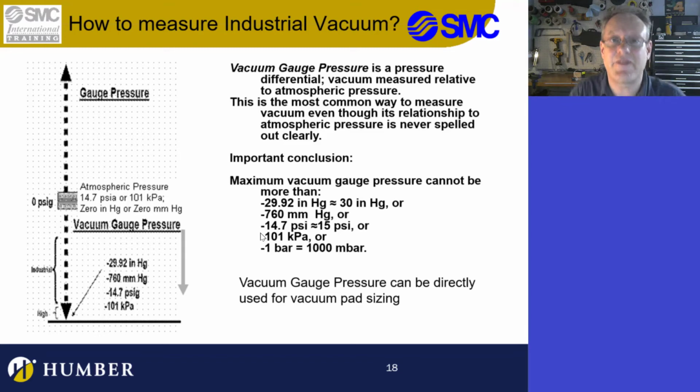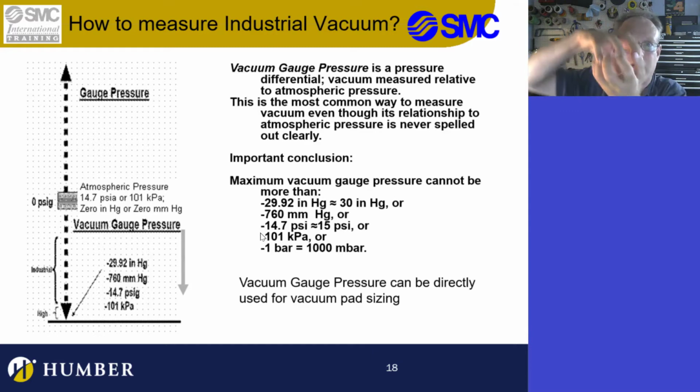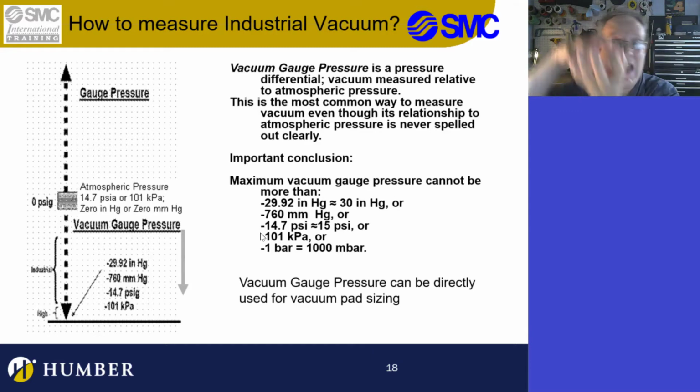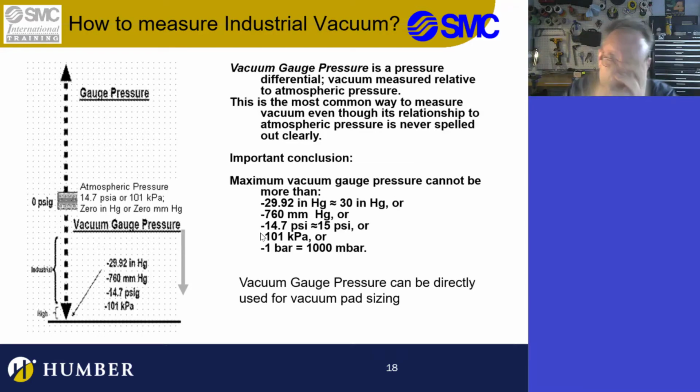Okay, so the difference, if I created a space, if I put, like, I don't know, here I have a vessel, pretend vessel. There's a vessel, and there's 2 psi in there. There's a lot less air pressure than there is out here. So the difference between the two is 12.7 psi. Okay, so there's actually 12.7 psi of pressure creating force to push that thing together. So we've got this difference.